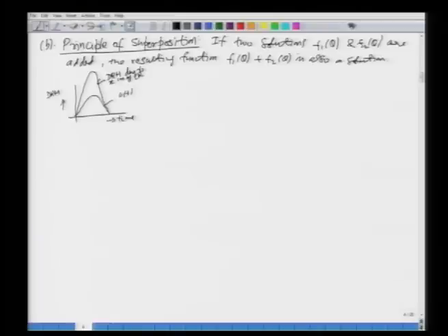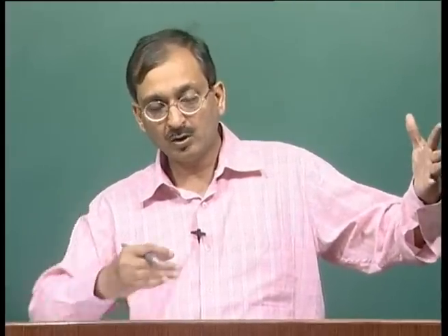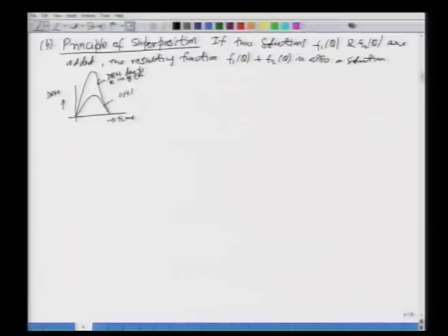So, you have a solution due to 1 centimeter of rainfall, and another solution, the DRH due to x centimeter of rainfall, also represents a solution of your system. The system is the same, but the input is different, so you can apply that different input on the same basic solution. That is why the principle of proportionality allows us to find the direct runoff hydrograph for an increased value of x. Now, this is as far as the proportionality is concerned.